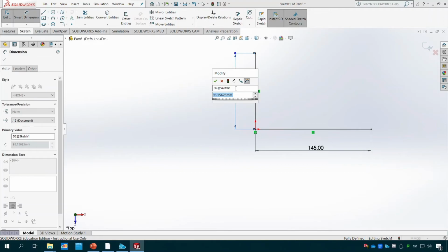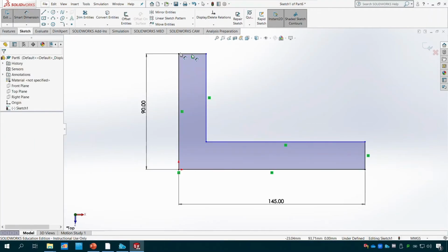What I need to do, I just need to make sure actually I go and reach back to the same line in here. So this one is important. Let me see whether you pick up. Do you see, for instance, this is the line it makes. It's quite common that SolidWorks does that. This is one of the, to be honest, common issues that you get, the accidental lines. Connect these two together, and hopefully it is vertical as well. Good. So what I need to do, I just need to say this one is 25.